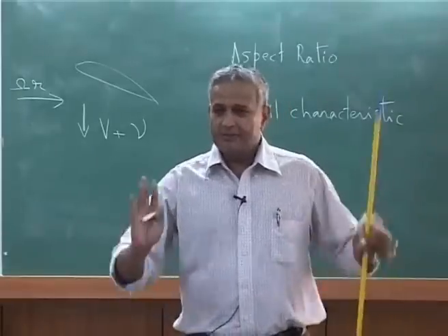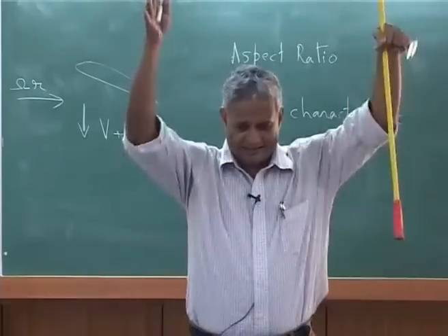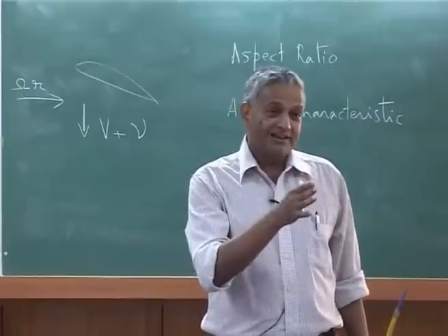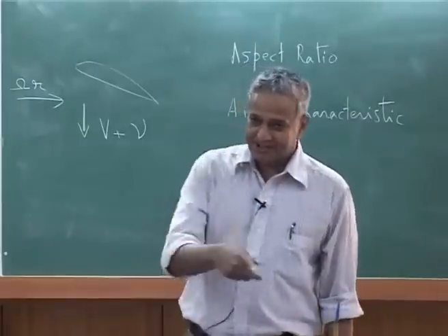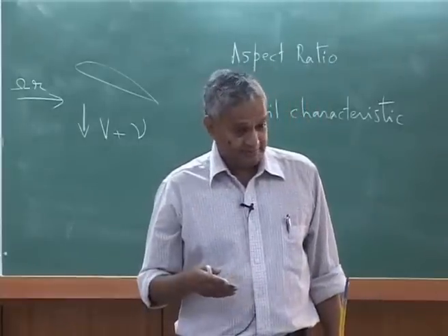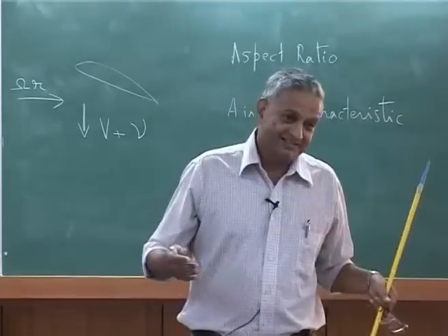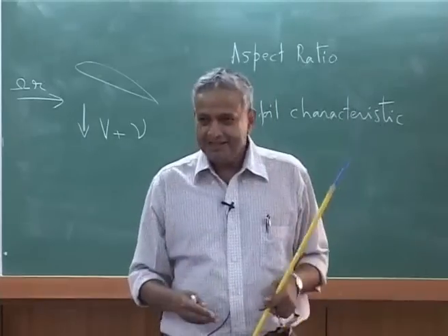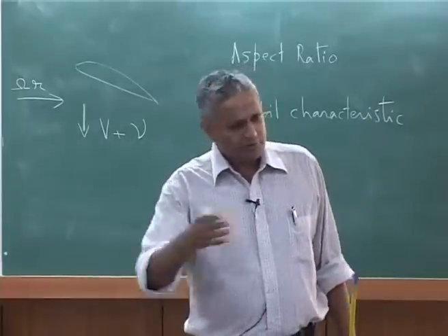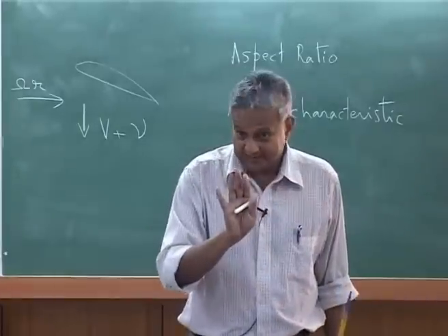But if you say I fix my structure of the vortex, it is going to be in a cylindrical, vertical cylinder, that is all, no deformation, then I call it prescribed wake. So either I prescribe the wake structure, that is relatively easy, but if I do not prescribe, I say okay, let it evolve by itself, that is the free wake theory, but it is more complex. Even prescribed wake, free wake, both are complex. Now of course people have developed their own computational codes using vortex theory.